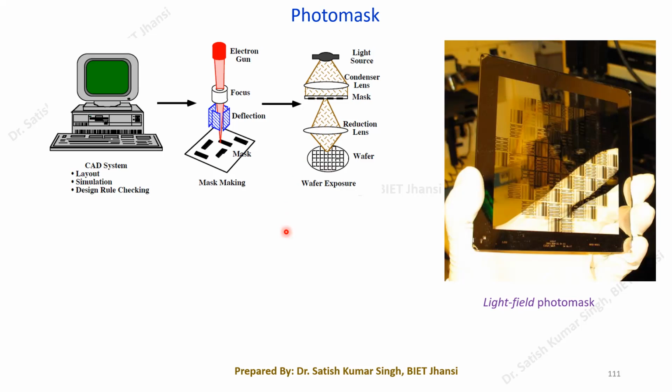So first of all, we have to look at what the different materials are. As I said, basically it is a fused silica, and onto the fused silica we have the chromium, and then this chromium contains a photoresist. That photoresist can also be an electron resist. So it can be sensitive to electron beam, or it can be sensitive to laser beams. Some other materials are also being used for photo masks.